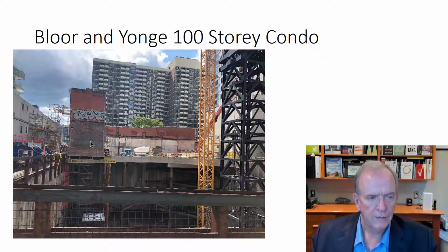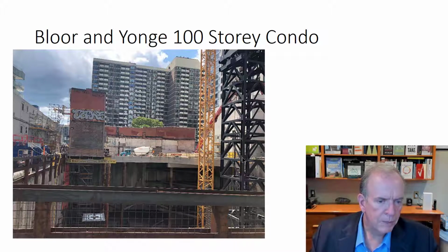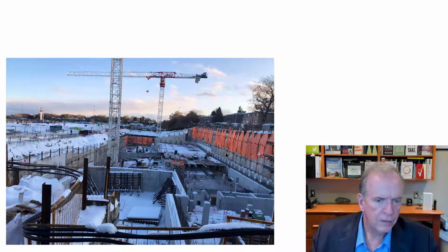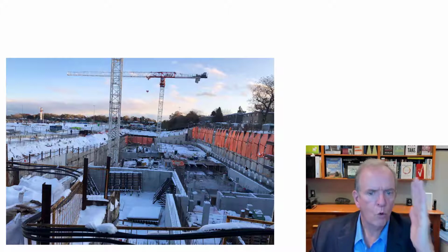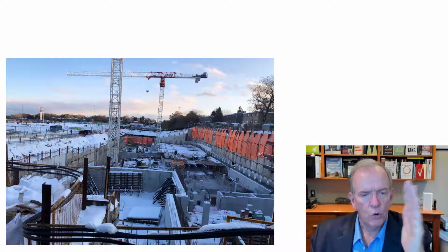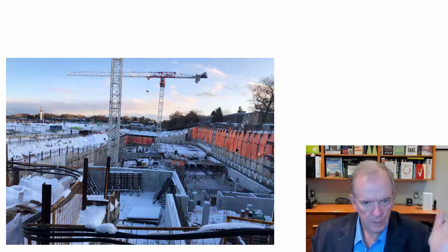I think I have to go back there. It's probably past that I can see things, but I think that eventually they ended up tearing this down, but I could be wrong. One of my students was telling me that when he was there, so I could be wrong. And because there's no space, what they have here is basically your tiebacks going in. You can see the rakers just off to the side. The tiebacks are drilled and grouted into the ground back, and that's holding the shoring from collapsing.